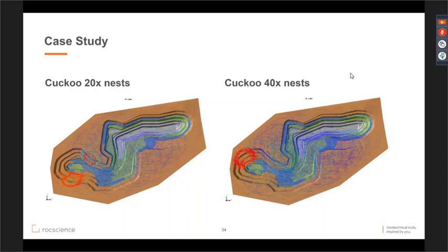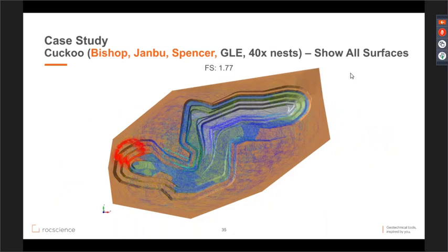The reduction in factor of safety in this iteration is attributed to the search settings, where the optimization function is based on all results of all critical factors of safety calculated for each analysis method. So it's recommended that you always compute with all 4 analysis methods selected and then report with your preferred method.